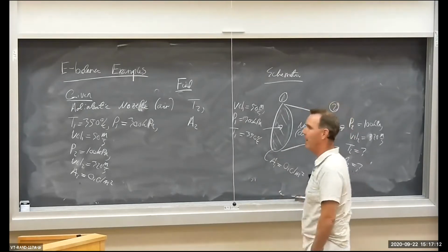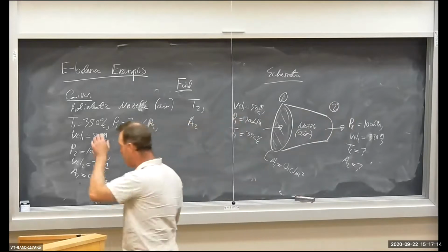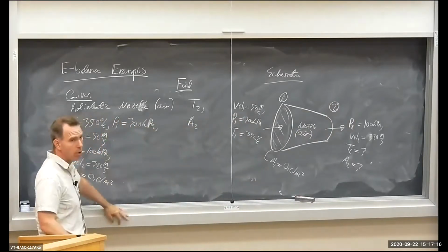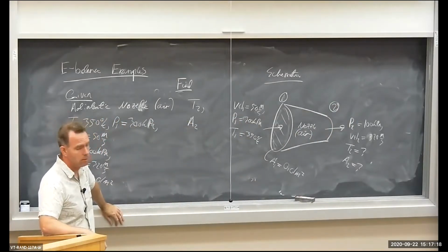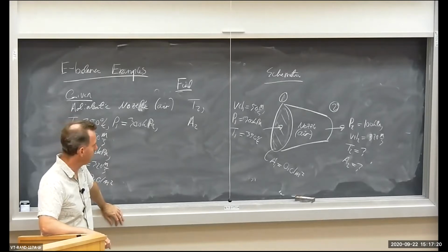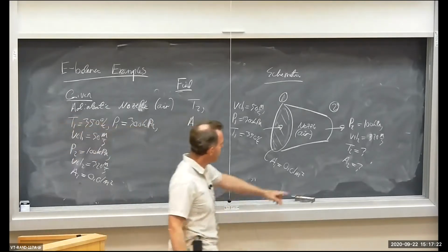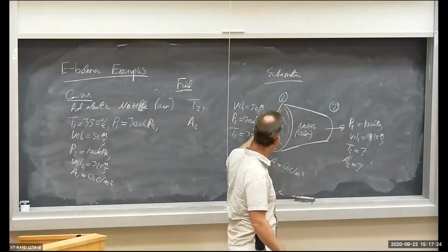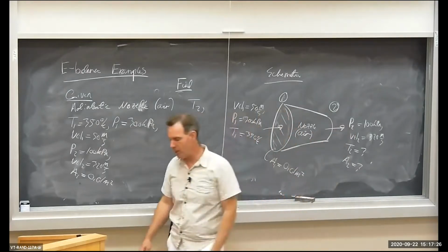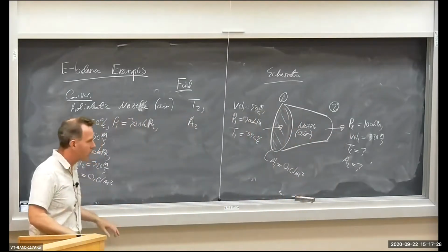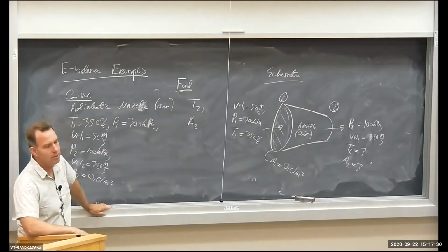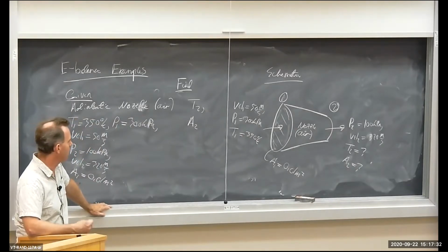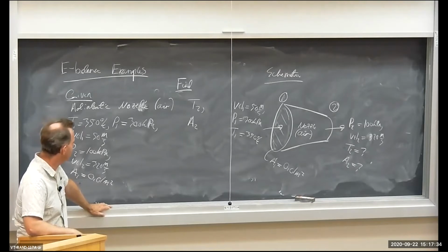How large does the outlet circular flow area have to be to accommodate the mass flow through the nozzle? After all, pressure and temperature are going to be different from the inlet to the outlet. So density is going to be different, and velocities, of course, are different. So we're going to need different flow areas, and we'll see this when we do the calculation.